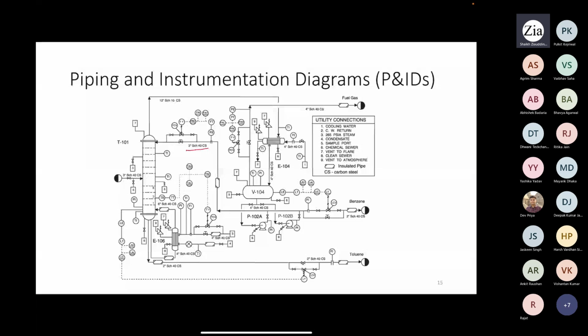And also you will have a lot of details to operate different equipment or process units when you talk about automation, because within your process system you will have a lot of valves and also different other operational units which will be controlled by different PLC, programmable logic control units, where some specific commands will be given based on monitoring different parameters. Suppose you need to adjust the pH. So in all process operations, very rarely you will have manual intervention to adjust pH.